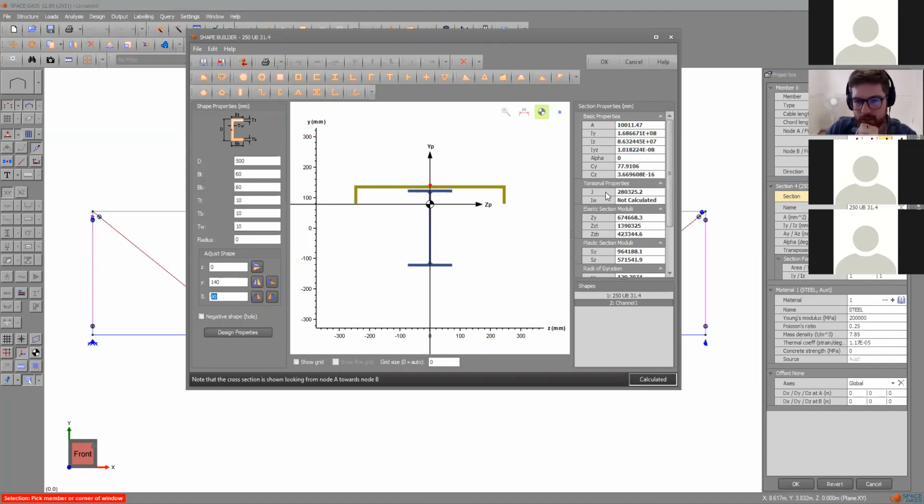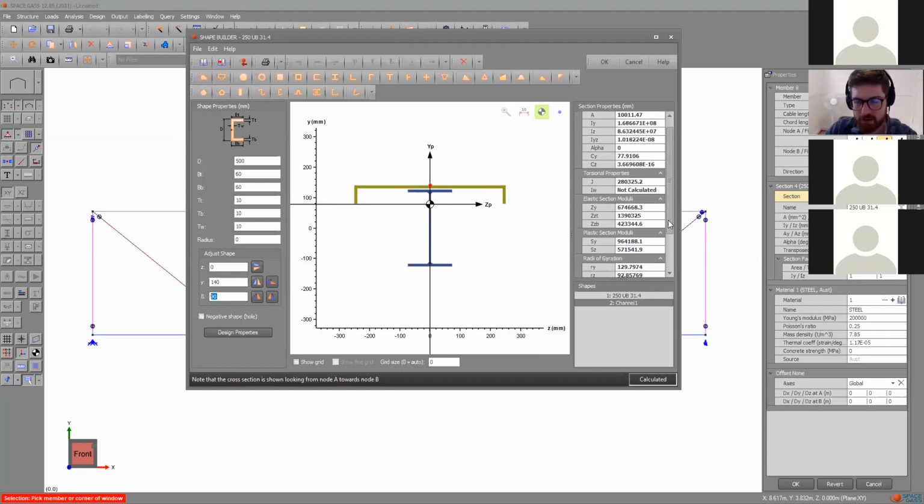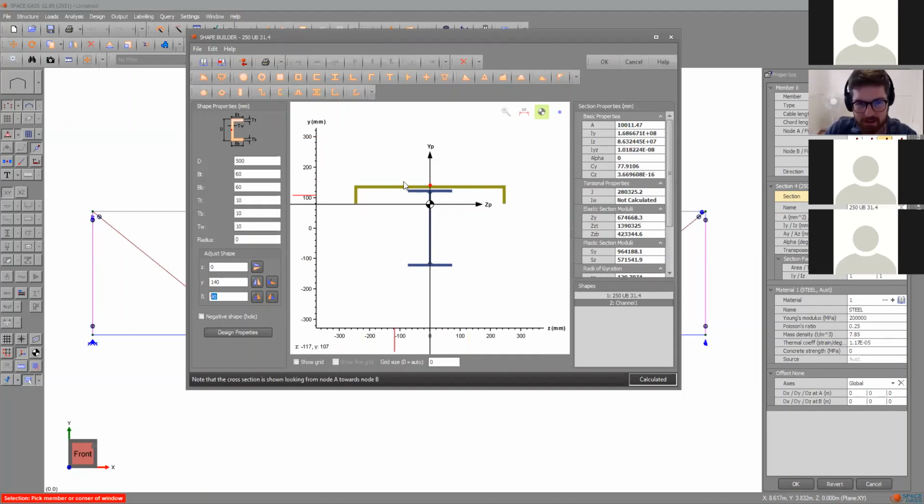Of course, you can calculate this all analytically, but I trust this software before I would trust any of you with a parametric spreadsheet. Saying that as someone who's written parametric spreadsheets to calculate all of these I-beams and C-section properties, I'm still finding mistakes in it. Having said that, of course, if you're calculating a custom element for a job with a pretty significant aspect or risk in that design, you always want to be checking these numbers that the computer is throwing up for you, simply because, you know, most analysis software is constantly being developed and constantly being bug fixed.